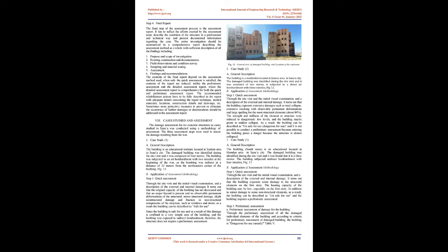Step 4, Final report. The final step of the assessment process is the assessment report. It has to reflect the efforts exerted by the assessment team, describe the condition of the structure in a professional and technical way, and present documented information regarding the case. The entire investigation should be summarized in a comprehensive report describing the assessment method as a whole with sufficient description of all the findings, including: 1. Purpose and scope of investigation. 2. Existing construction and documentation. 3. Field observations and condition survey. 4. Sampling and material testing. 5. Assessment. 6. Findings and recommendations.